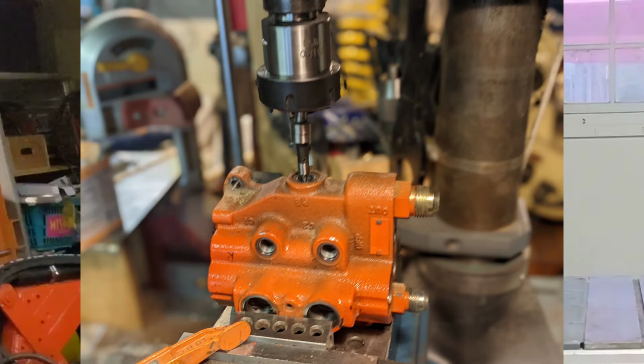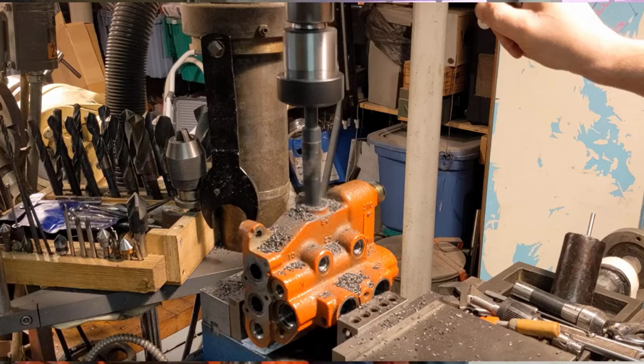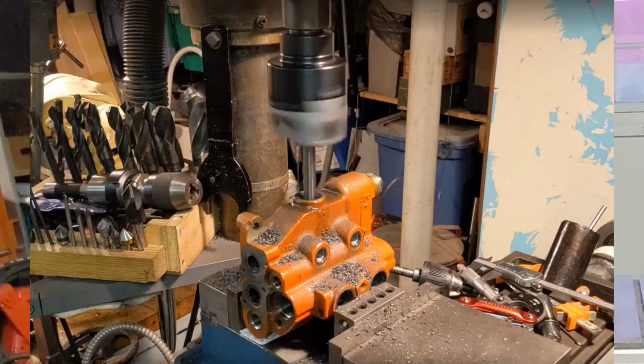So it was time to mount the valve into the mill vise. I got it carefully squared up and centered on the internal pressure galley. First we'll create the inner bore in the pressure galley, so I drilled to a size about 100 thousandths under the final diameter I was looking for, and then used the boring head to open it up to its final finished size, using a snap gauge as I went along to measure my progress.